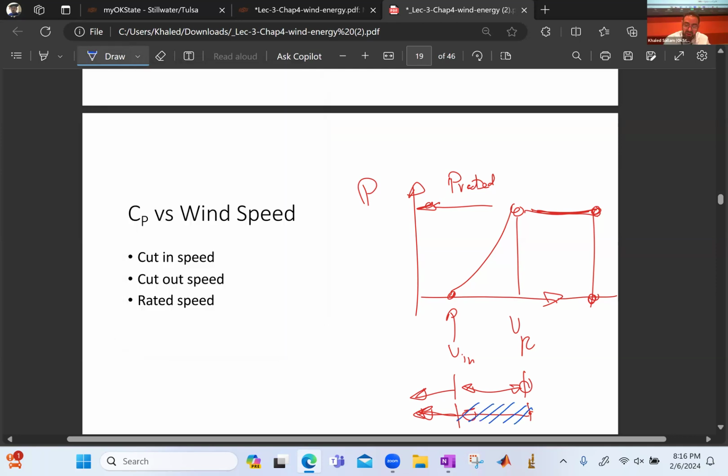So in this range, you can tell yourself, I can live if I have more turbines than what I need. So what do you mean? Like I want 10 megawatt for that city or that village. Okay, buy not one turbine, buy 3 of those turbines, so that if all of them are producing 1/3 of their rated power, you will still be able to get the full load. And anyway, you're going to buy more than the rated power.